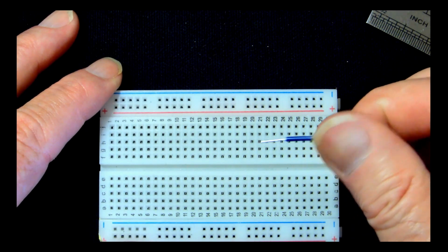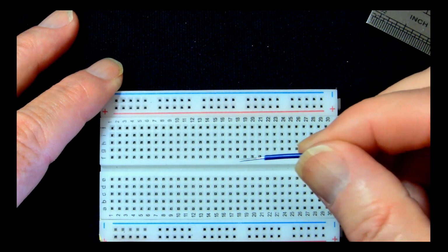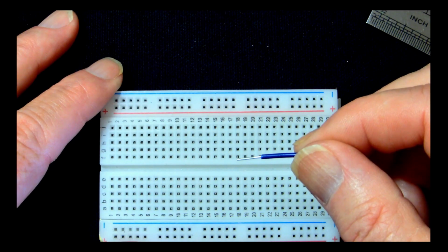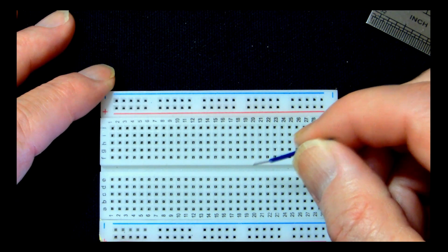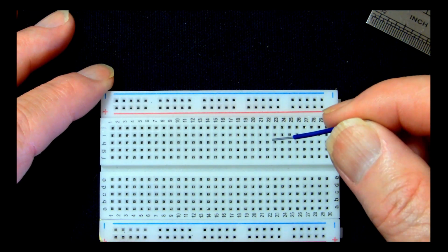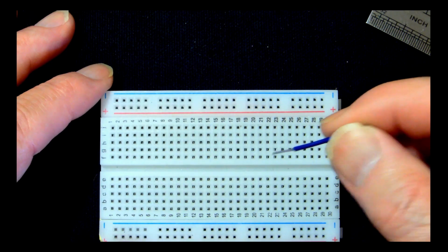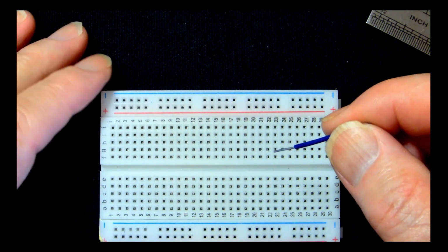I use standard AWG 22 gauge. Now that is slightly over the 0.6, it's about 0.64 or 0.638 or something like that. But through several years of using breadboards, I've never had any problem, and they've been used in multiple projects. The breadboards that I will use are £10 a piece, and I've got good ratings, so always check the ratings, always go for good ratings.